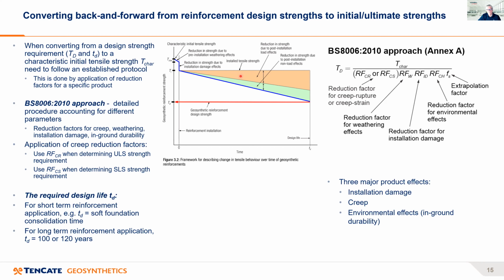This next one is if you apply a constant load to the reinforcement, it can lead to a reduction in strength due to creep. And then the second one here is a durability effect where the reinforcement can be buried in the soil, and over time it also may have an effect on the reinforcement. So it's these three areas, installation damage, creep, and environmental effects, which can have a significant effect on how the reinforcement behaves with time.